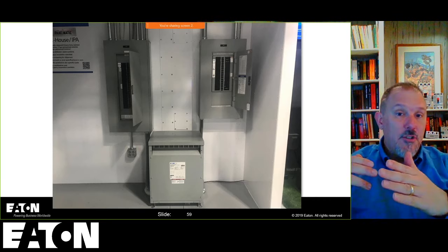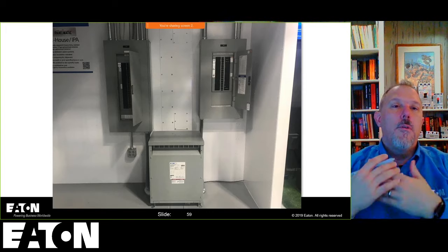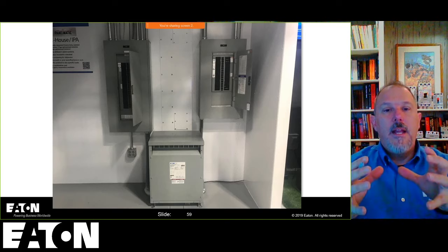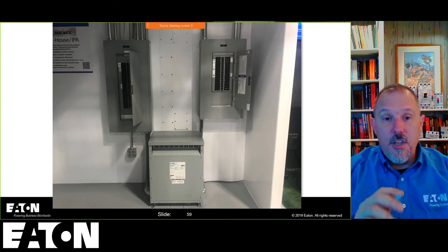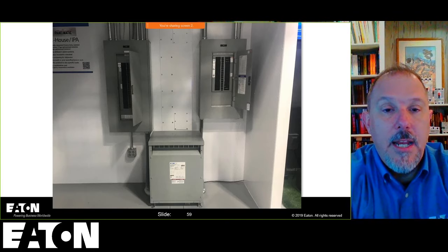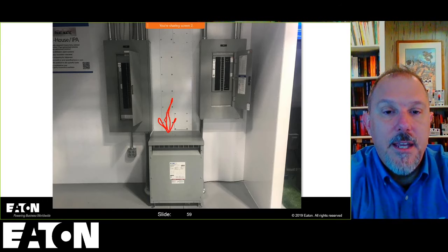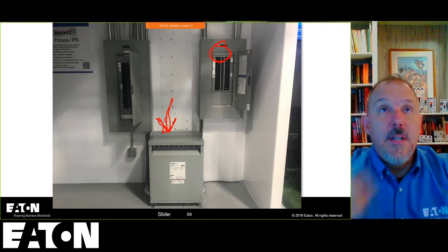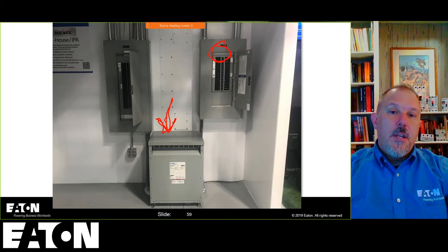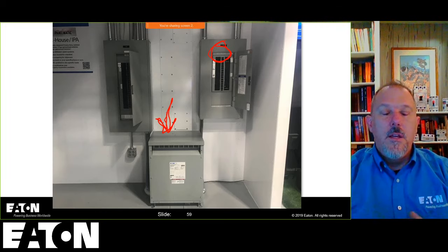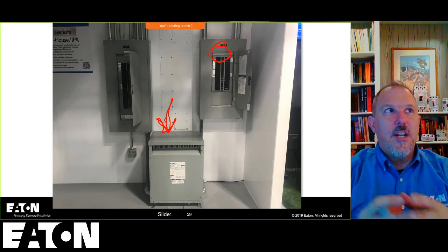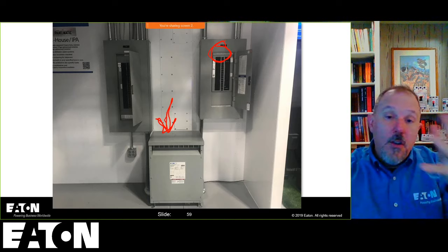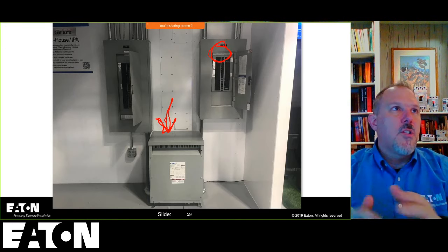So you still have an energized. So you want to promote de-energizing that entire panel board. And I could make an argument that by locating your overcurrent device in this and taking it out of here will increase the safety because you're driving the electrical worker to de-energize that entire panel. I don't know if you agree or disagree, but I could make arguments on both sides of that.